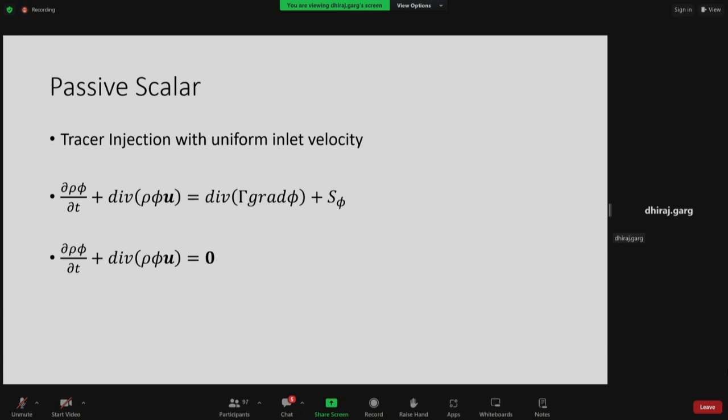Sometimes steady state simulation is difficult, so people have used transient analysis and run it for a long time. The last time step or longer time step, whatever solution you are getting, is technically the steady state solution. So it can be an engineering way of solving the same problem in a different way if the solver works easily in unsteady state. So far, so good for this part.